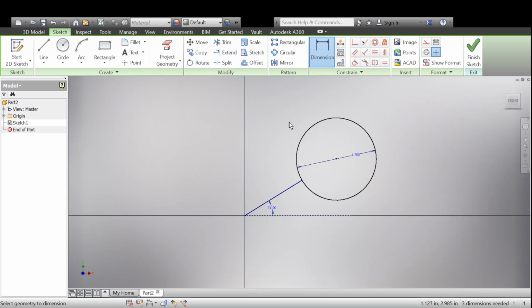I'm going to use the Dimension tool. I'm going to hover on the line and click it. I click and let go, and then I move away from the line. Now, the way I clicked it, it's letting me define a horizontal dimension. I don't want a horizontal dimension. I want the actual dimension. So let me click and drag away. Why is it only giving me the horizontal dimension? I'm going to click the endpoints of each part of the line. I'm going to click this endpoint, then go over to here to click the other endpoint. And it's still giving me the vertical dimension. Why is that